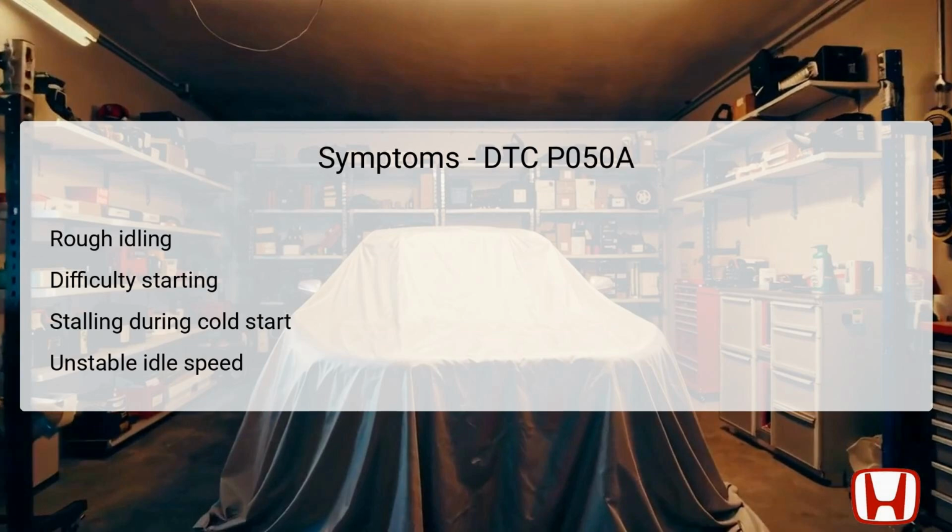In severe cases, stalling can occur, particularly right after starting, when idling is crucial for maintaining momentum and stability. Unstable idle speeds may also arise, suggesting that the ECM is struggling to maintain the balance of air and fuel required. Recognizing these symptoms early is vital to prevent further complications and ensure the vehicle operates smoothly.